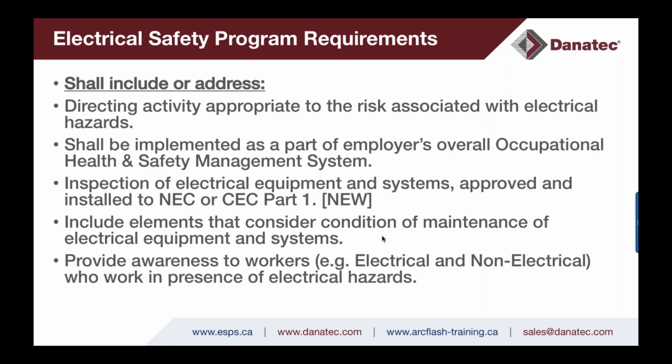This work task table uses condition of maintenance and then implies likelihood of occurrence of an arcing fault or an arc flash. The previous use of that table in the arc flash PPE category table method would imply arc flash PPE required. Well, this table again was removed from the arc flash PPE category table method and made a separate table to be used under the arc flash risk assessment requirement.